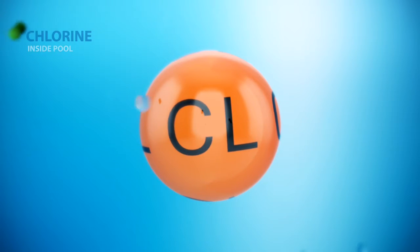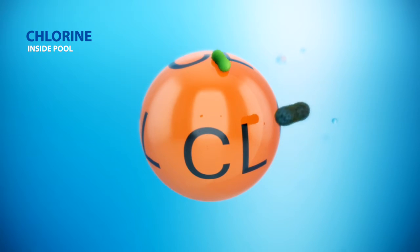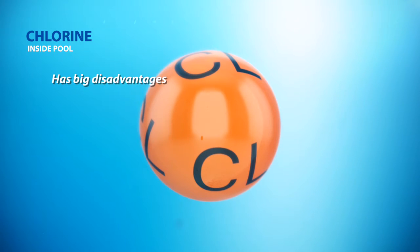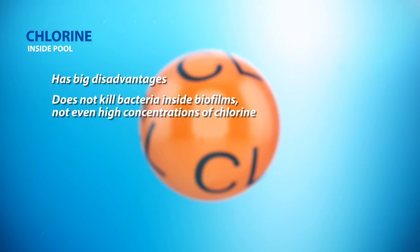We need to use chlorine because it's the only disinfectant that will kill bacteria quickly. However, it has some disadvantages. It will kill most bacteria in the water, but not bacteria growing in biofilms or in bacterial floc. Chlorine forms disinfection byproducts which are toxic, especially when they become volatile and pass from the water into the air.